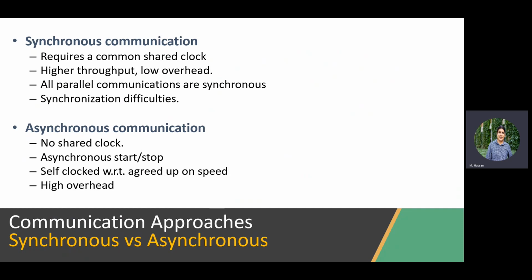What is the problem with synchronous protocols? Again, synchronization is not easy to maintain because you have to drive the same clock. They must be completely aligned to be able to operate correctly, right? This alignment is hard to achieve. In fact, in unrelated matter, if we talk about modern DRAMs, DDR4, DDR5, etc., one of the basic problems that is preventing them from really achieving higher speeds is this synchronization that is needed between the off-chip memory, the DRAM, and the actual CPU, right? So this is a fundamental problem that is being faced there because DRAM is a synchronous memory. It's called SDRAM, synchronous DRAM, right? So which means it's driven by the same clock speed as the memory controller on the chip.